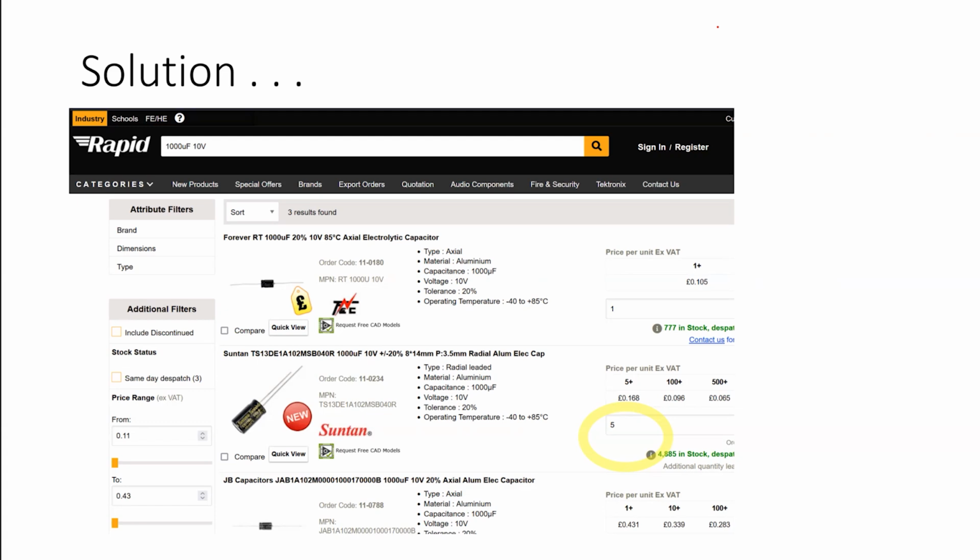And the more voltage overhead you can give, the better it is. So 30 pence, or effectively nothing, and I popped a new capacitor in it. The power supply went back to working as normal. I popped it back into the function generator and it's still working as normal.